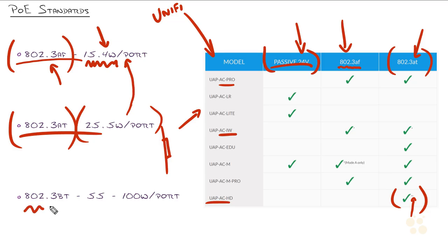Now there's one coming out that I'm kind of excited about, but I'm not too sure how to take it. 802.3bt. And with the power of video, maybe by the time you're hearing this, it's already out there. But look at the power capability it's able to produce, 55 to 100 watts. Now, initially that sounds awesome. I'm like, good grief, we can just plug our computers into an Ethernet cable and not even have to worry about power throughout our building.